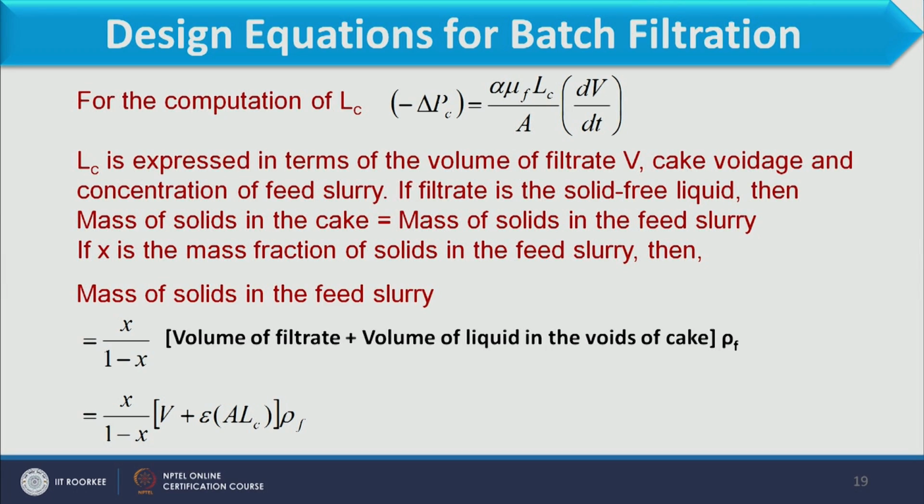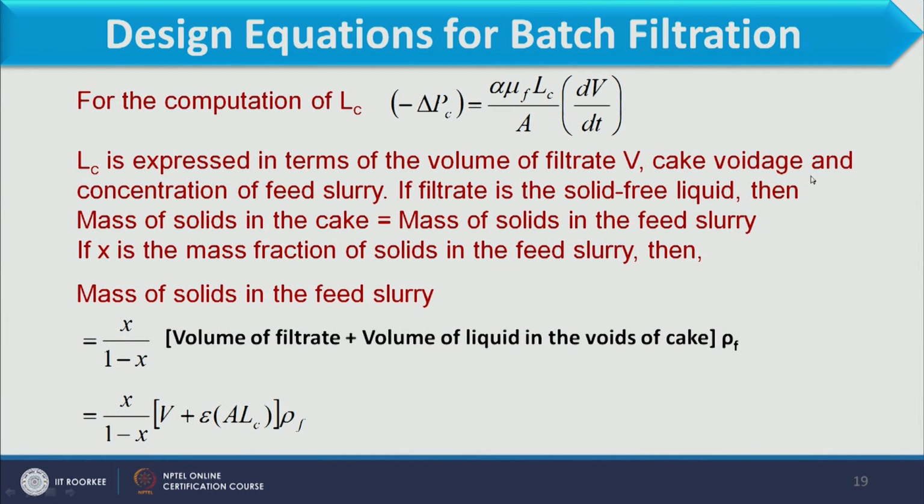Now in this slide we will derive the expression for Lc, which is nothing but the total thickness of the cake. So Lc is expressed in terms of the volume of filtrate, that is V, cake voidage and concentration of feed slurry. If the filtrate is solid free, then we can say that the mass of the solid in the cake is equal to the mass of the solid in the feed slurry. As we have assumed that the filtrate is solid free, whatever mass is available in the slurry, all that mass will be accumulated in the cake. So we can equate these two.